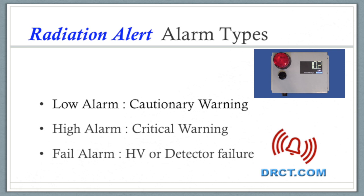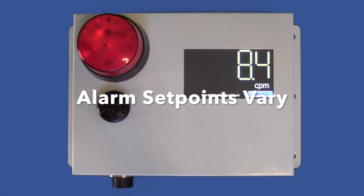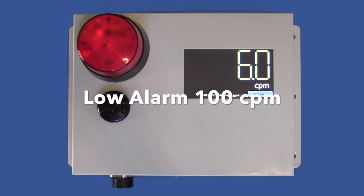Fail could mean that the high voltage has failed, the detector has failed, or has been disconnected. The fail alarm is activated when readings fall below the set point. Recommended alarm set points can vary with different models and different applications. Please note, for this demonstration, we temporarily set the low alarm to 100 CPM for display purposes only.